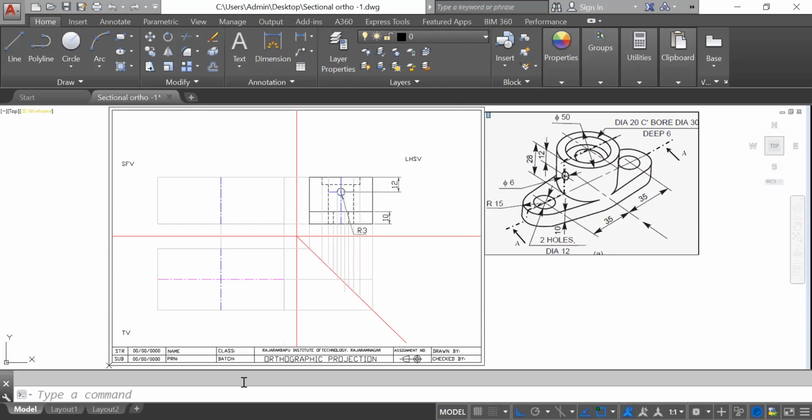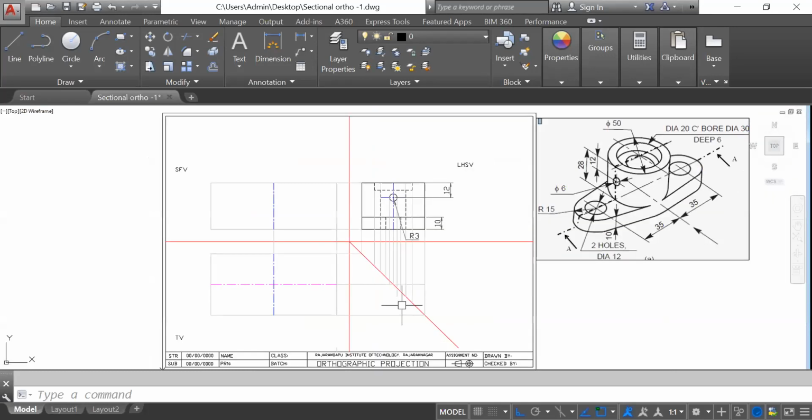I have already drawn the side view, because you will not get enough time to prepare the side view. So that's why I have prepared it already, and according to the different dimensions, I have prepared the blocks. For the front view, 100 by height 38. Then total 100 and width is 50. In the same way, I have taken projection of the height from front view and length and width from top view. So you will get this one. I will just delete this part.